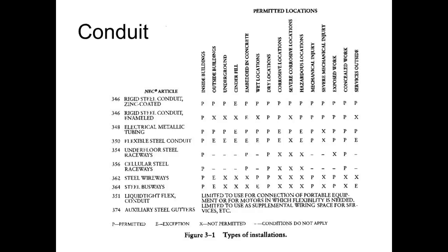They'll use a lot of RMC in industry too, in industrial applications, not commercial applications. Commercial applications use a lot of thin wall, whereas in industrial applications you usually use RMC or the rigid metal. Underfloor steel raceways, cellular steel raceways, steel wireways, steel busways, liquid tight flexible conduit.